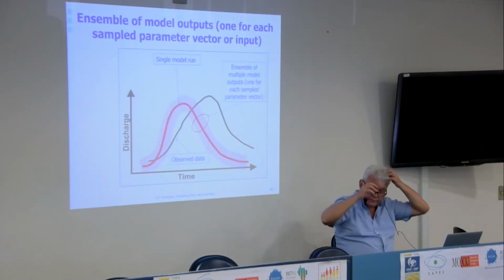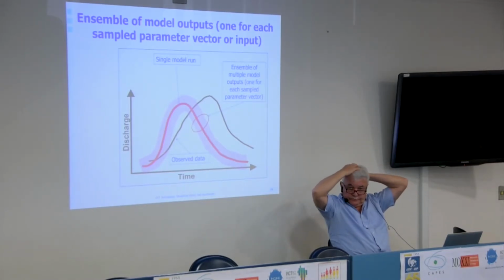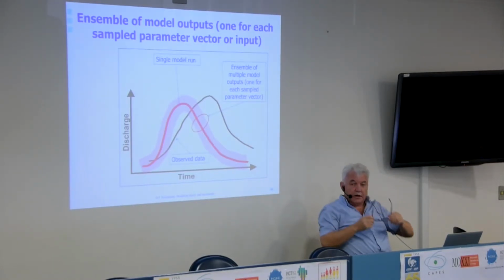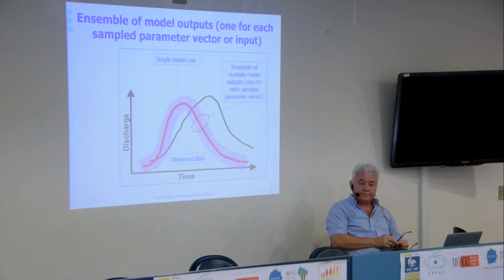You can make a step-wise procedure. For instance, in Brazil, like in other parts of the world, we have big uncertainty in the rating curves. Yes, the curve that we use to transfer the water levels into discharge. One stepwise procedure is perhaps introducing this uncertainty transfer analysis, not only making the random seed